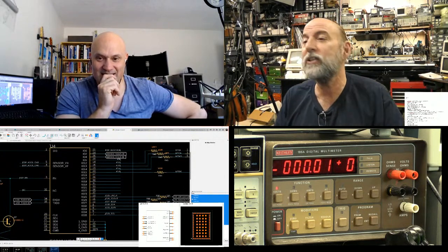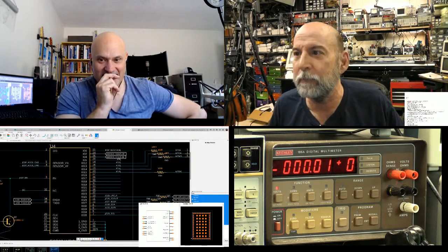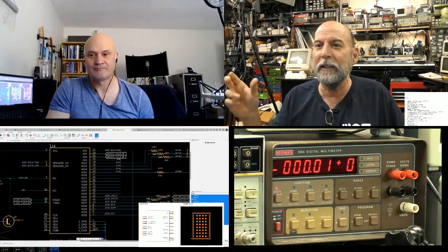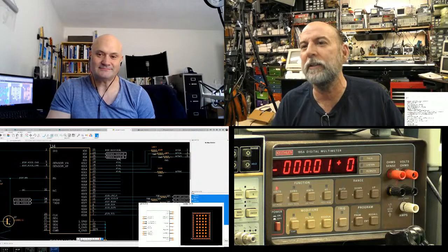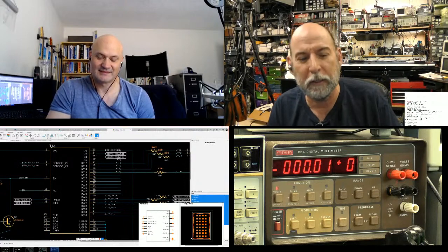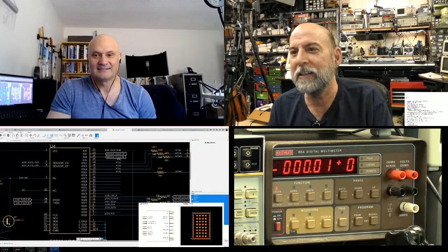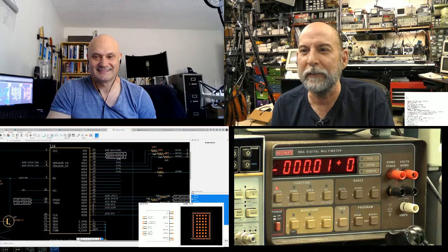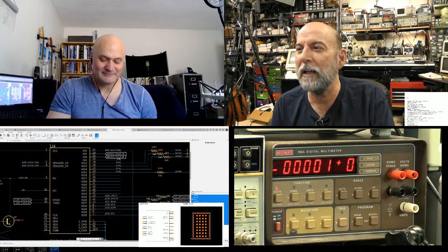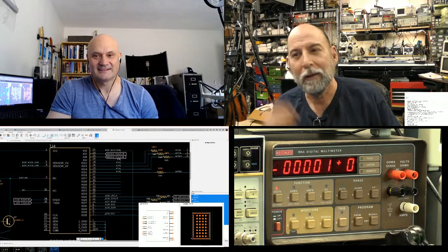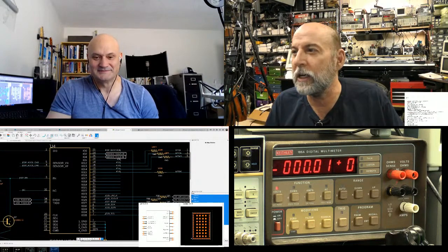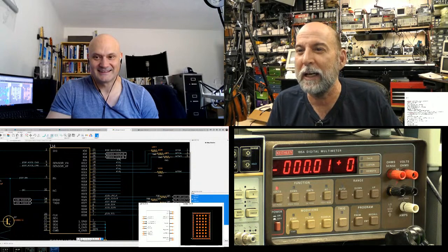Matter of fact, that's a subject of a whole other conversation, because I got a USB to IEEE interface, and I could get some things working and other things I couldn't. I couldn't get the auto zero function to work on one of my meters and stuff. And it's like, how did they get this stuff to work in the old days? Plus you get a hell of a ground loop through your data connector. That was another problem. Yeah. I know that because I touched it and the ground at the same time and got shocked.